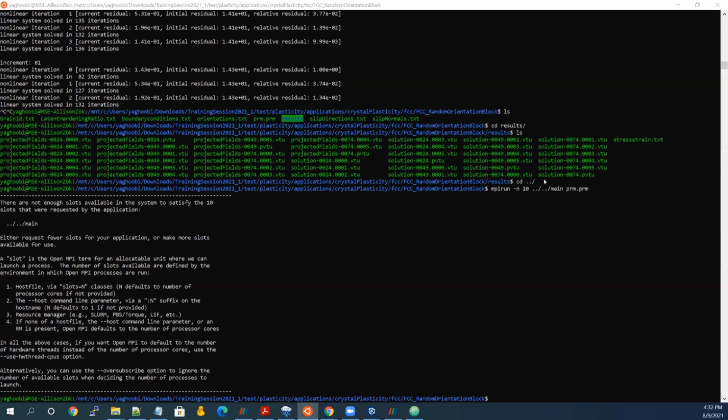You can add a column to the orientation file and define your residual stresses as an eigenstrain, and then relax the sample without applying extra boundary conditions. Just fix it to not move around with the residual stress. Do the relaxation phase and start your real simulation after that.